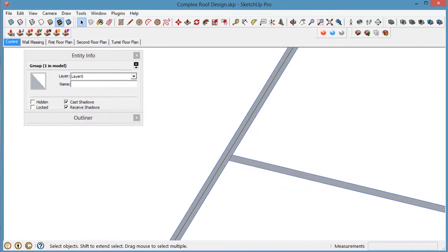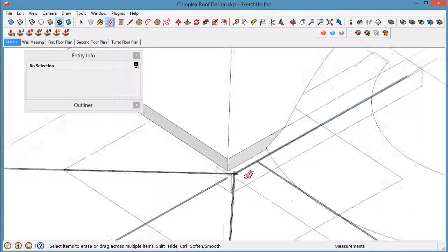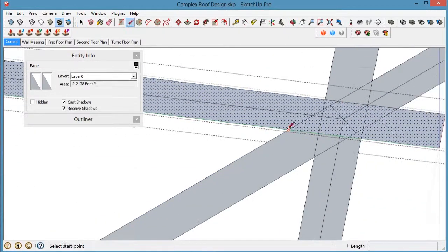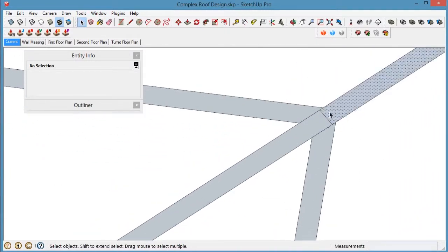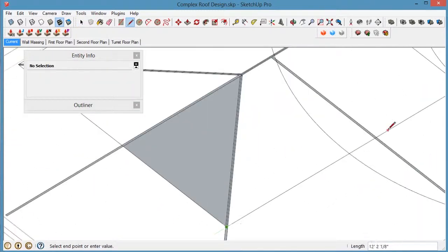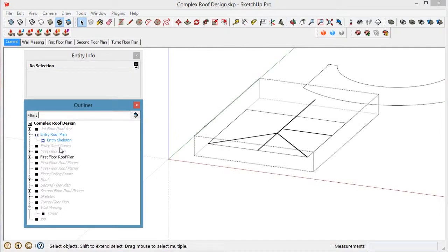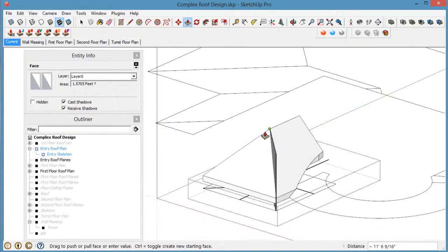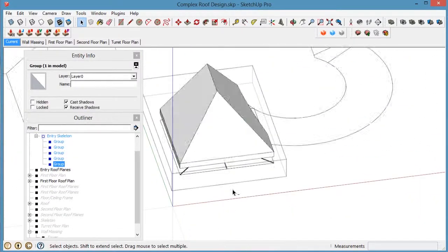We'll create the roof plan here. And after drawing and distributing the two-dimensional skeleton members, we edit them so that they have the correct intersections in preparation for extruding them. Then we extrude them to a height above the top of the roof.